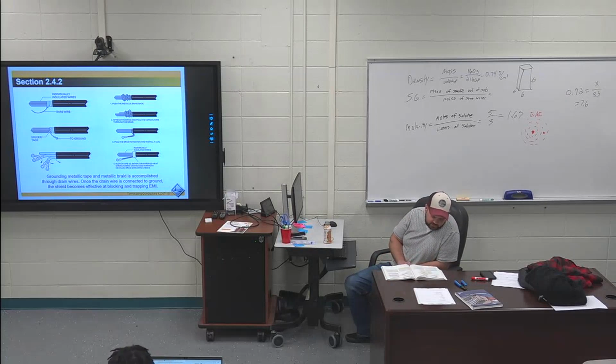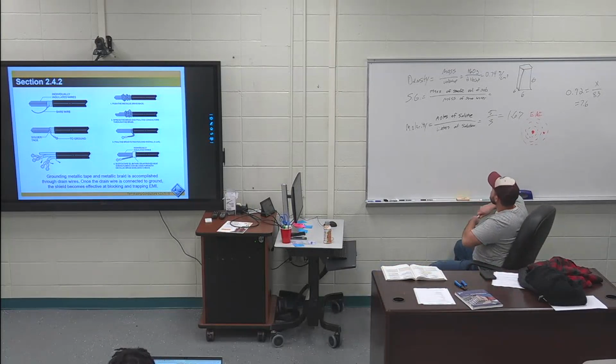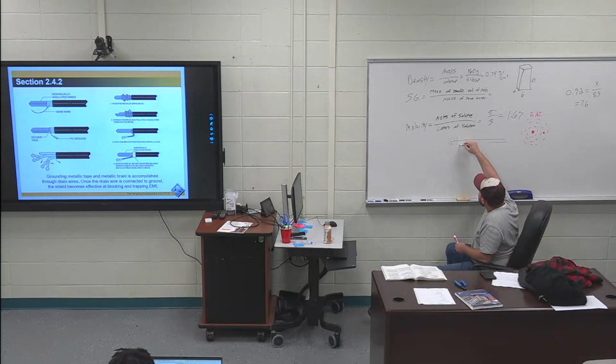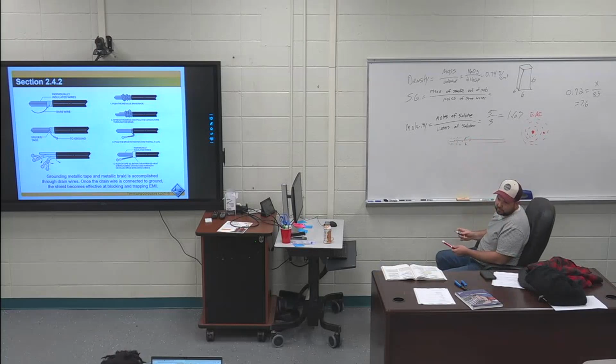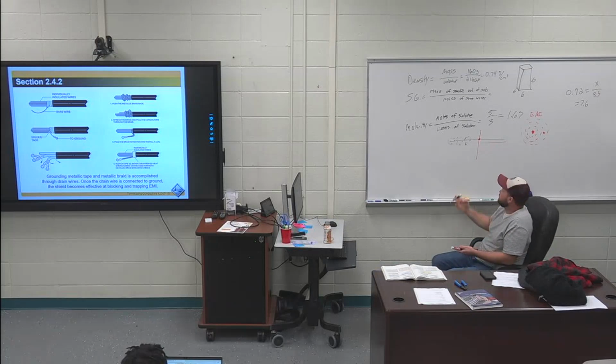Still going along with this, page 38, first bullet point on page 38: where unshielded cables of different signal conditions must cross, they should do so at right angles, not gradually over long distances. So if I have two wires running alongside each other, and say my black wire is my power wire, and I have EMI, I do not want to run them parallel. I want to run straight across this so that there's only one point where that electromagnetic interference can interfere with my communication cable. That makes sense? So that's what it's saying, run it at a right angle, 90 degrees, rather than parallel.